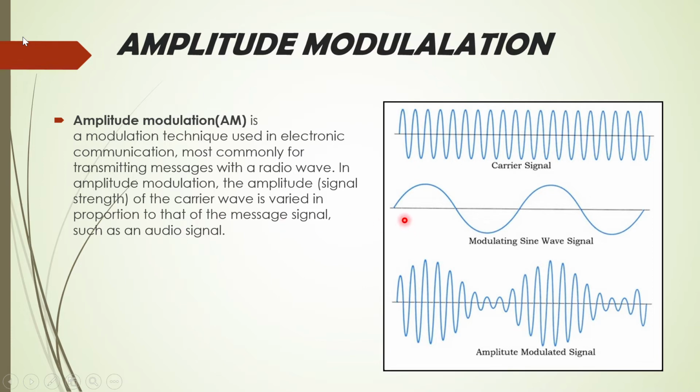What we basically do is mix our audio signal with a high frequency carrier signal to get a resultant amplitude modulated signal, and these are propagated using towers. It is the function of the antenna to then convert these AM electromagnetic waves into an electric signal.